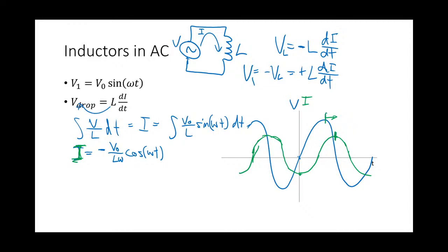So qualitatively, we can say that for the inductor we can use a mnemonic like that. The voltage, wait a minute. Yeah, the voltage comes earlier than the current. That's right. The voltage leads the current for an inductor, and we use the word ELI. So to put both of those together, I know it's a little silly. Oh, the integration constant, we know it's 0.